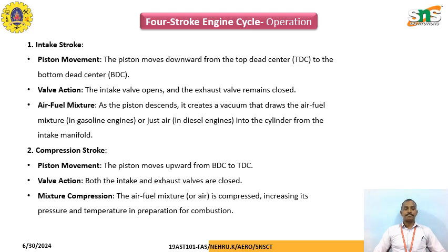Intake. Piston movement: the piston moves downwards from the top dead center to the bottom dead center. Valve action: intake valve opens and exhaust valve remains closed during this stroke. Air-fuel mixture: as the piston moves down, it creates a vacuum that draws the air-fuel mixture in a gasoline engine, just air in a diesel engine, into the cylinder from the intake manifold.